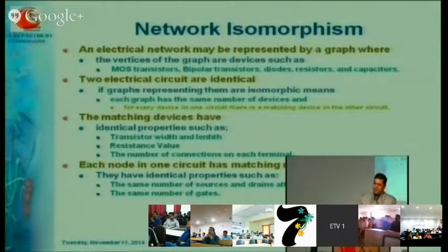That schematic is created either with the help of gates or with the help of transistors. Once the desired schematic is ready, the next part is we create its spice file or deck file, and then we take that deck file in our microwind software, we compile it, and then we generate the layout of that particular circuit. So now you have two circuits, or two networks, with you. One is your schematic, another one is your layout.